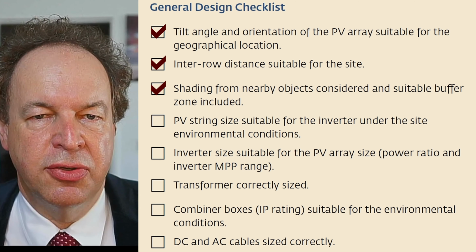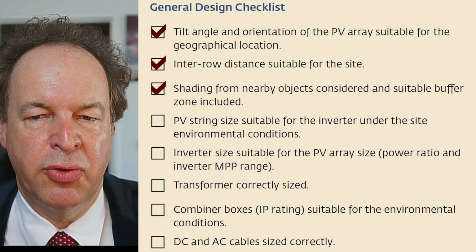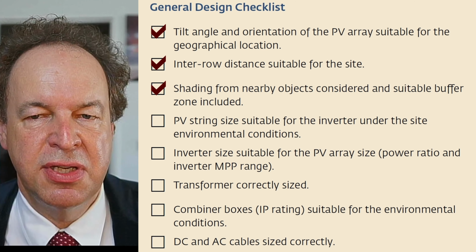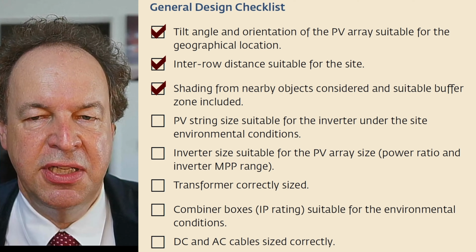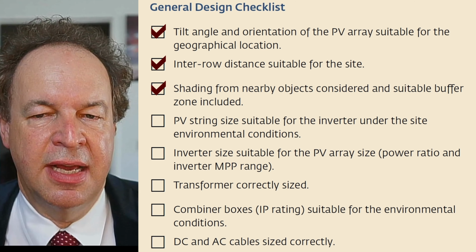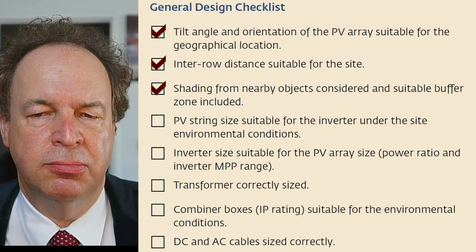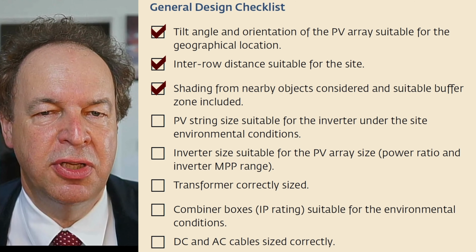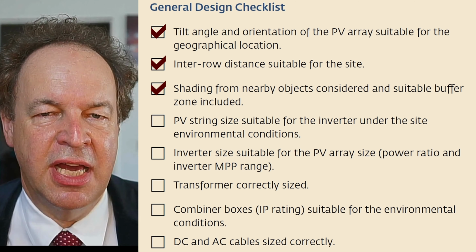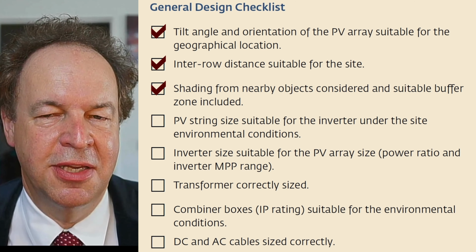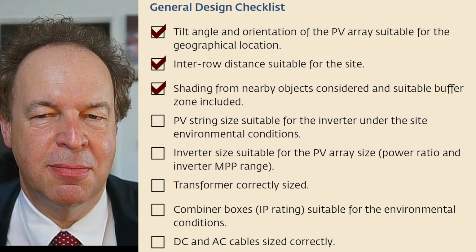Shading of obstacles or nearby projects, this could be some buildings or trees and so on. We also have to take into consideration that if you have young trees there, in 15 or 20 years the trees may grow and then cause shadowing. But some simulation programs like PVSol include that. You give in the type of tree and it already calculates the future size of the trees and the possible shading.